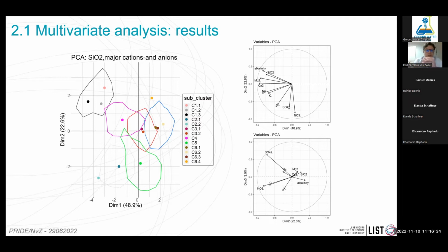So just to quickly give you a bit of background, our catchment has 2 plateaus or 2 hill slopes. The one is what we refer to as the primary hill slope. This is the largest part of the catchment, but then we have a smaller secondary hill slope. On the secondary hill slope, the soil layer on top of it is homogeneous, but on the primary plateau, we have quite a significant weathering front. But what is interesting is that this weathering front has a cutoff in terms of elevation. The base of the weathering front you can observe on the hill slope. So below this on the hill slope, you have unweathered rock.